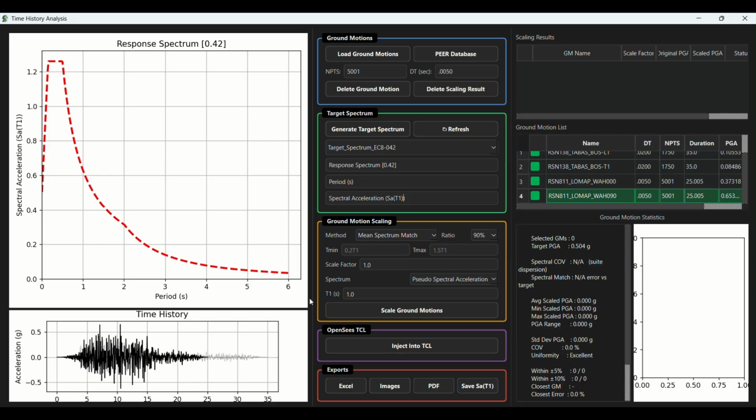Scaling adjusts each ground motion's intensity to match a target spectrum over a period range relevant to the structure, rather than applying each record at its recorded, as-is intensity. Every loaded seismic record is checked by default here. Uncheck any you want excluded from this particular scaling run.